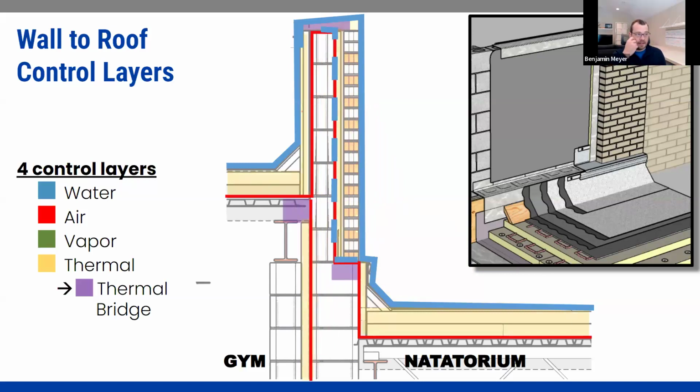And then insulation, and again, it's pretty tricky here. So we have continuous insulation at the roof coming up this parapet to the shelf angle. So this is actually pretty important. Lacking this shelf angle gets even colder. And if your air barrier truly does this and it allows the natatorium air to get into these CMU cores, you really have a lot of condensation.